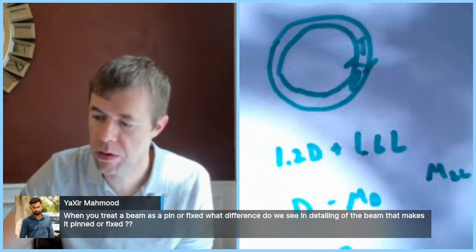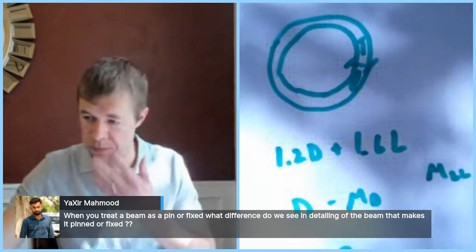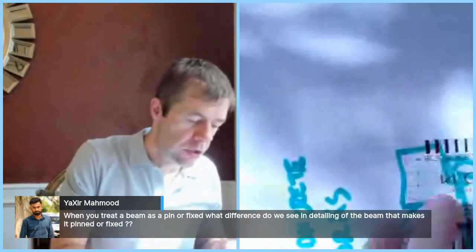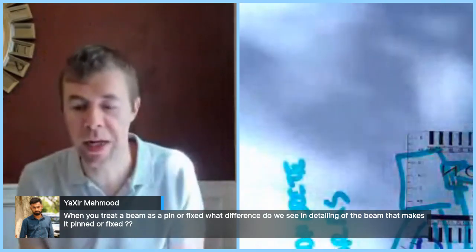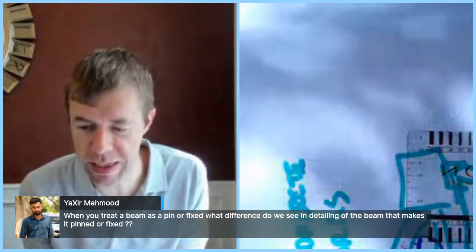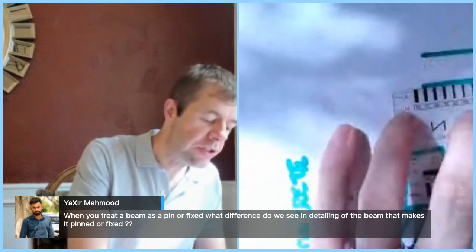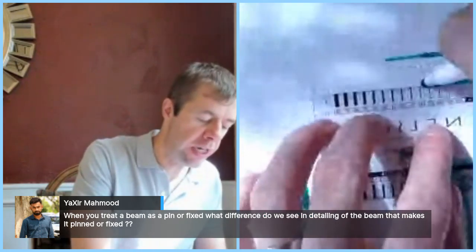Good question. So actually, the simple answer to your question here is, when you treat a beam as pinned or fixed, what differences do you make in the detailing? So a fixed beam just needs to have steel wherever there's tension at the support.